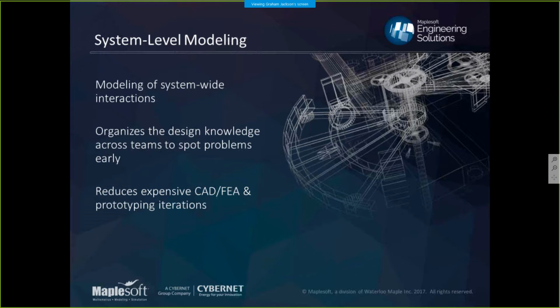Of course, FEA is very important, and it can help with specific parts and give you specific information you need. But with the system level modeling approach, you gain insight into exactly which local area you're trying to optimize with certain FEA processes, and you can do so in a very resource efficient way before you start dumping a lot of resources into an FEA process.